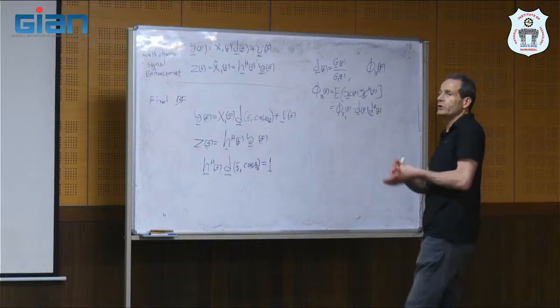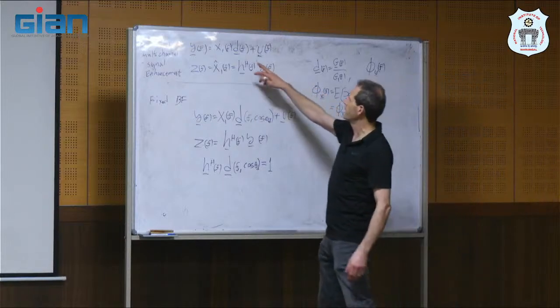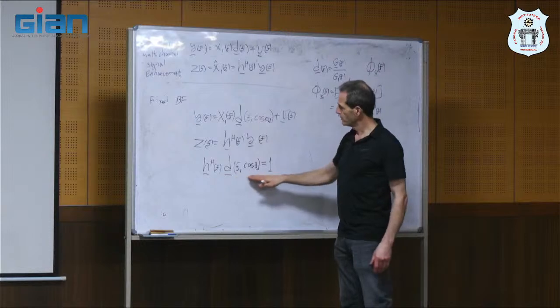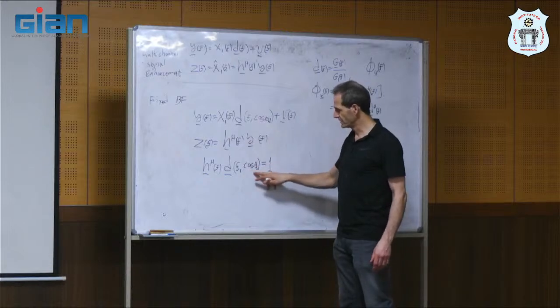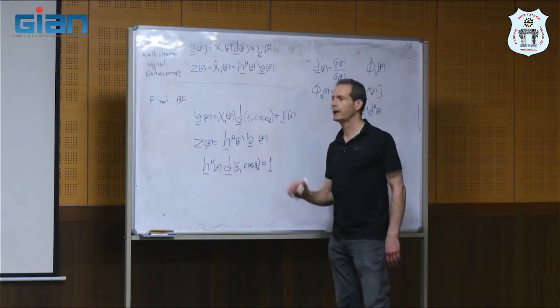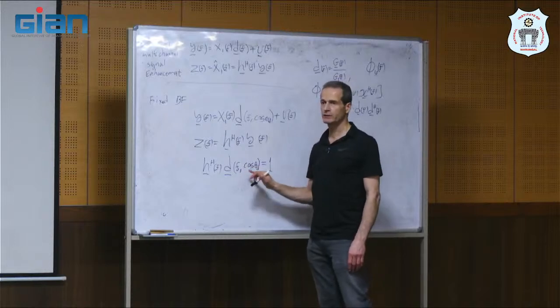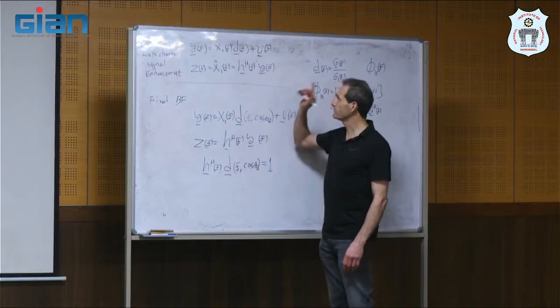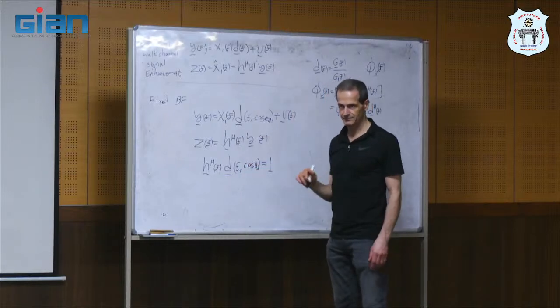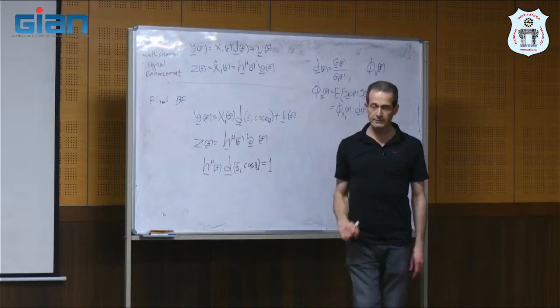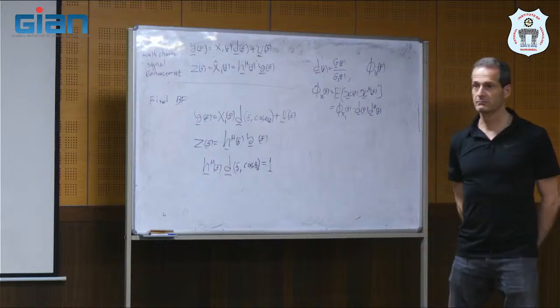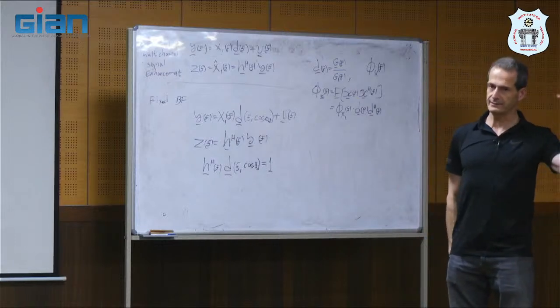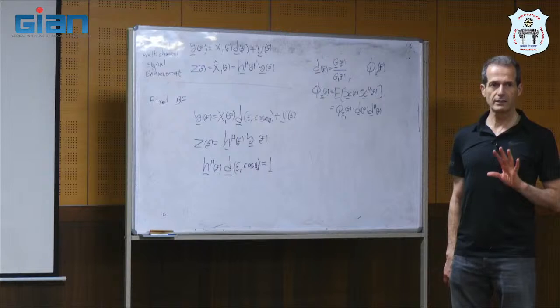But because we don't know the environment, we don't know the relative transfer function, we just know or design the beamformer towards a certain direction, theta d, this is what we apply. So this is the distortionless constraint, which is different than what we used here. In addition, I don't know what is the noise environment because I designed it in advance without knowing the environment.